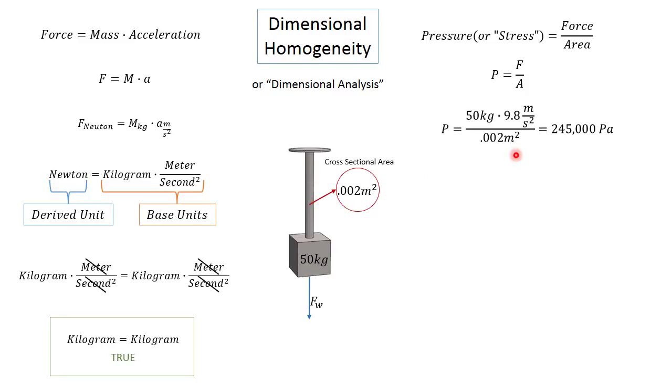But before we go to our boss and say, hey, I did the calculations, we're all ready to go, you're a good engineer, so you're going to do a dimensional analysis to help verify this equation. So just like we did over here, the first thing we do is remove all the values and any variables and just leave the dimensions.